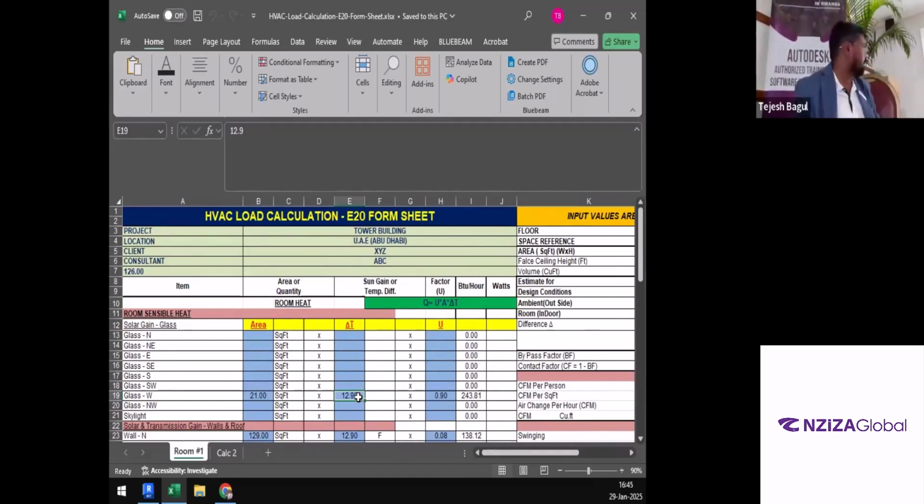Make sense? All right. Now, talking about the U value. We are talking about this equation to begin with. We can call it the holy grail of the HVAC industry: Q equals U A delta T, right? And the U over here is the thermal transmittance between your facade element and the indoors. The facade element, in this case, is the glass facing the west direction specifically.